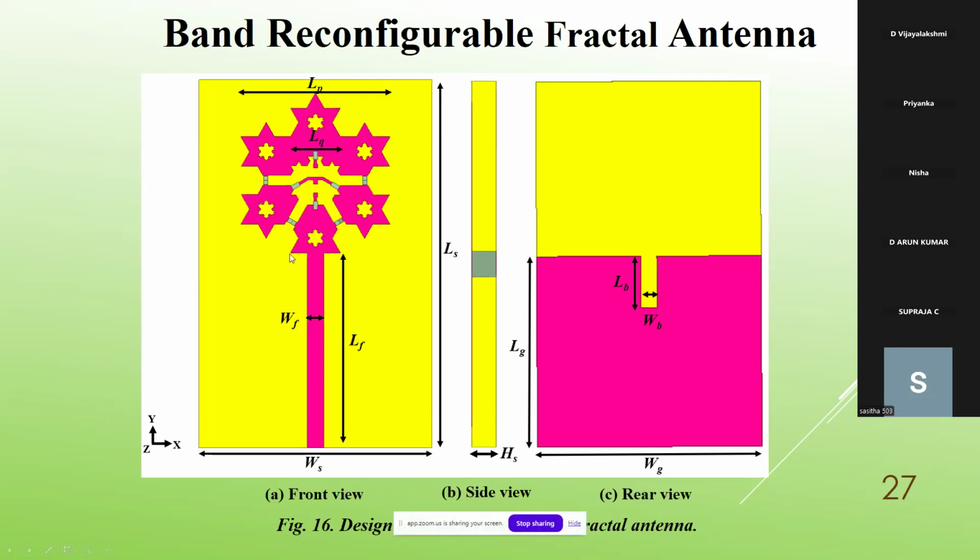This is the complete design, but with diodes. This is one diode, this is another: D1, D2, D3, D4. Four diodes are used, and 1, 2, 3 biasing lines are there where we can apply DC voltage. Along with the DC voltage, ferrite beads or inductors help to pass the DC and block the AC components or antenna currents.